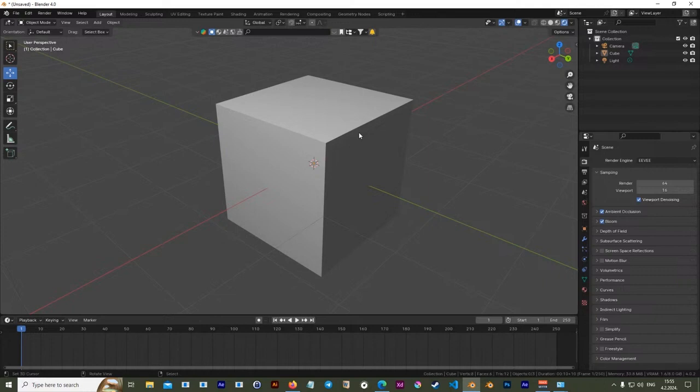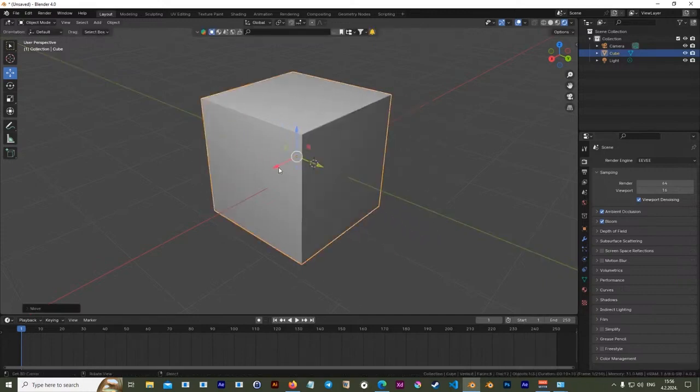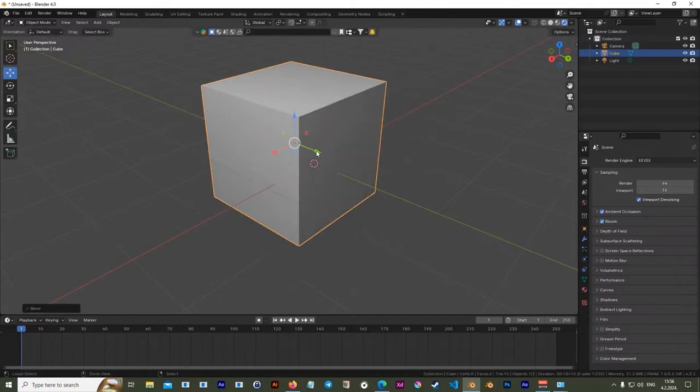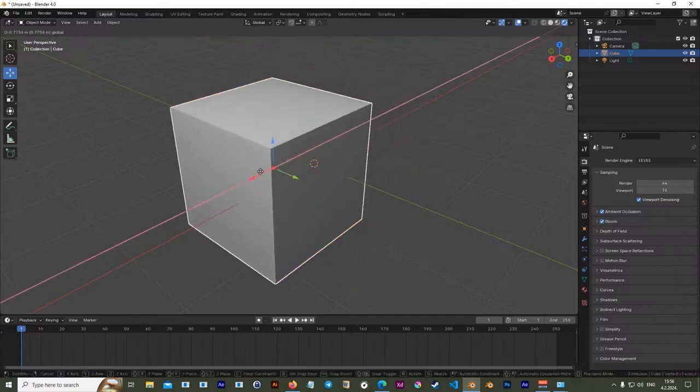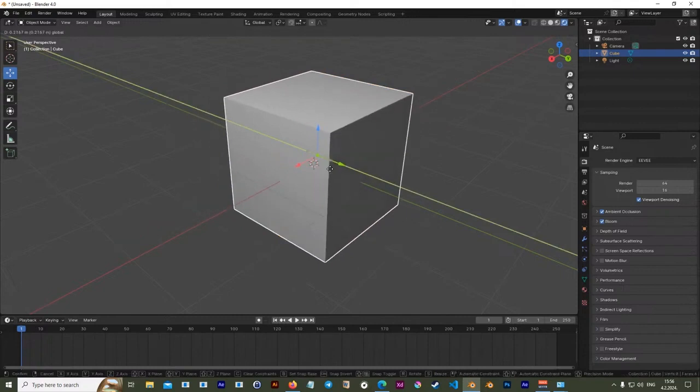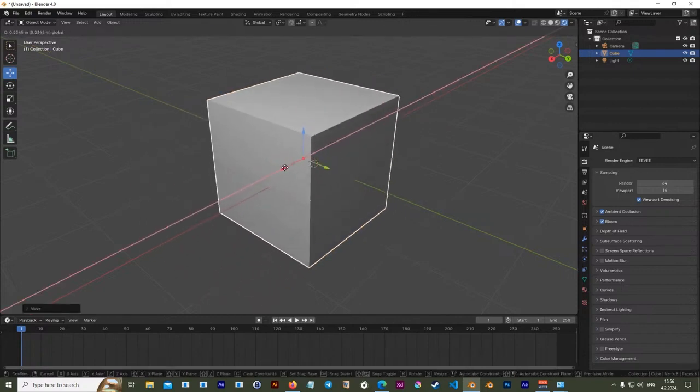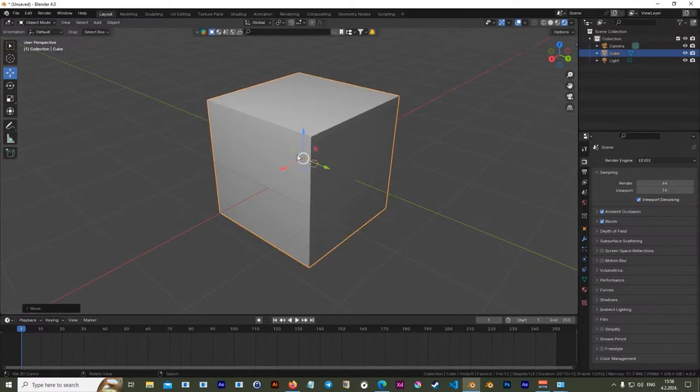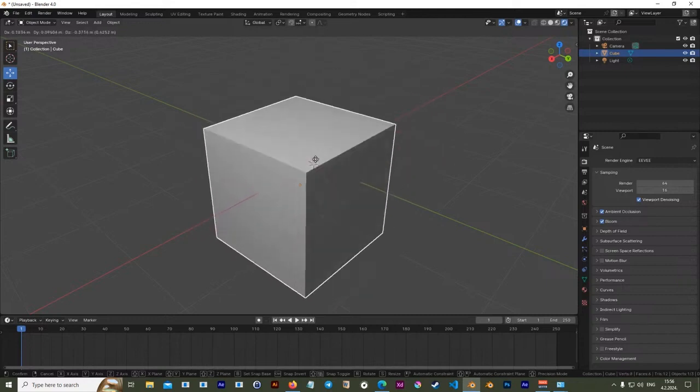So let's start selecting things. In Blender you select with the right click mouse and move objects with left click mouse. You can also move with right, but this is the way. Another way, so you can work almost without the mouse, is to have an object selected, press G, and now you move it.